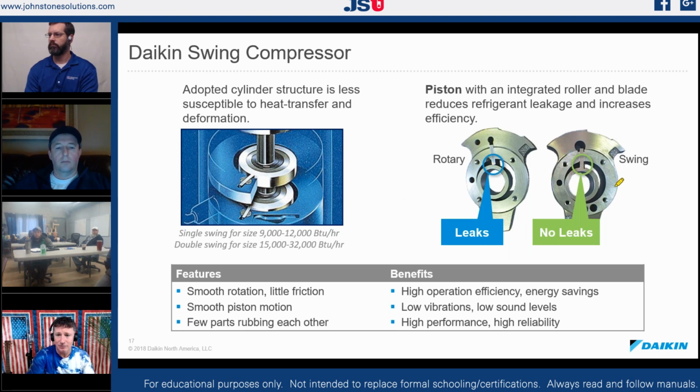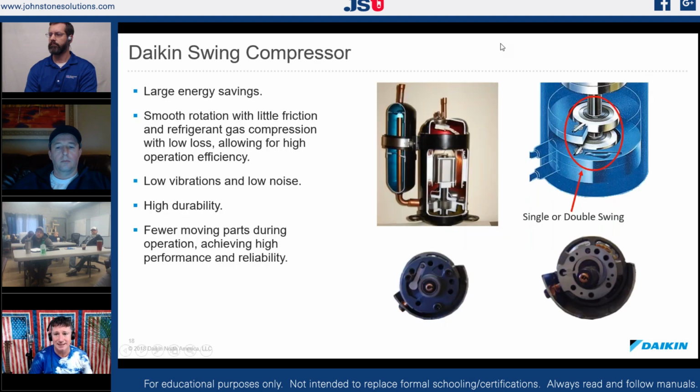What Daikin has done is they've redesigned that rotary compressor. They've made this solid and used a pivot point up here, so we don't have the friction that was going on right here in a traditional rotary. They took a design that was a very good design. Rotary compressors are very efficient compressors. They took that philosophy and increased the efficiency of the pump, which in turn increased the efficiency of the total compressor. So a very nice design.